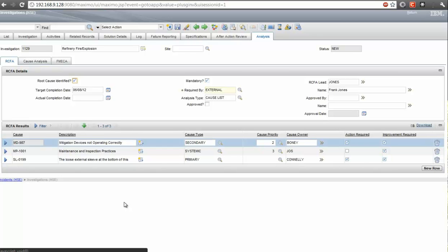So let me put a little more context behind this now that we're at this point, so you really understand what happened. This is actually a real-life use case. This company, in their refinery, had an ethylene process where they would extract ethylene gas from a raw source substance. It was one of the gases that they refined out. As part of this process, every 12 hours they'd depressurize that line, switch processes, and reverse flow to dry out the line. When they did this, temperatures would change significantly, so the pipes would expand and contract.